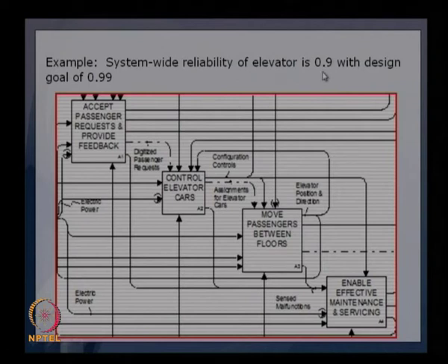So, that is the requirement, but we do not know how much value we should give for this, this, this and this. These are the 4 components, and we can do it with the apportionment method. We will try to divide this reliability amongst the members depending on our knowledge about the system and how it is going to affect the whole overall system. Accordingly, we will try to provide the reliability values for this.